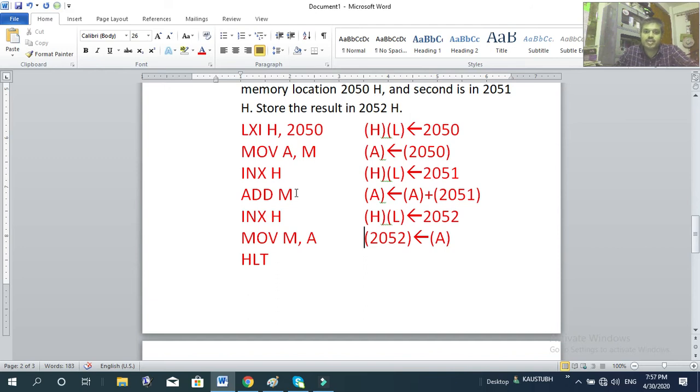Now the point is how will we check whether there is a carry generated or not? As during my last video where I explained the branching instructions, as I mentioned, there are only 8 different conditional branching instructions for jumping within the same program, by which we can check whether a particular flag is set or reset. So there are 5 flags. Out of those 5 flags, as I mentioned earlier, the auxiliary carry flag cannot be used for conditional, or if-else statements, because the auxiliary carry flag is the middle carry. So here we are looking into the end around carry, that is the carry flag.